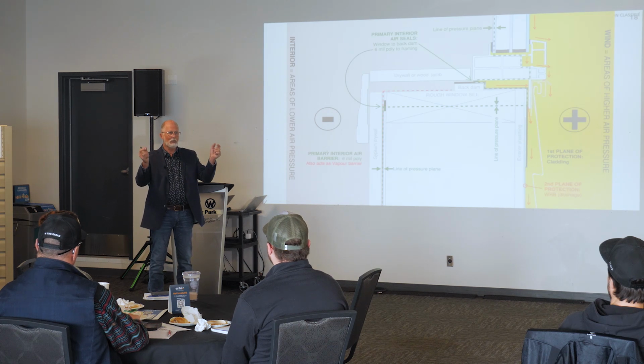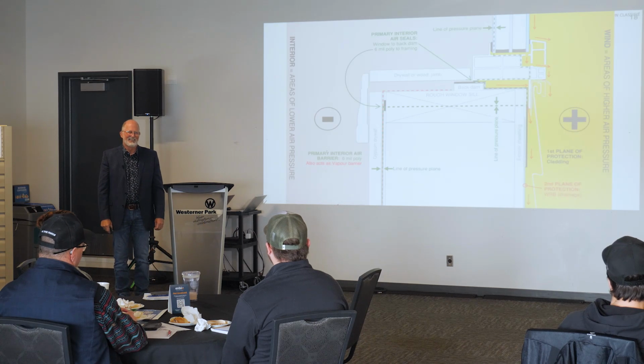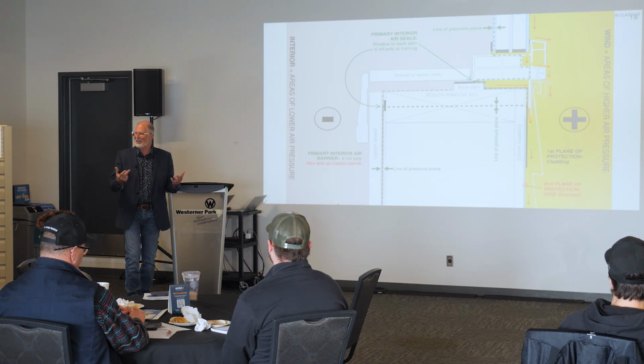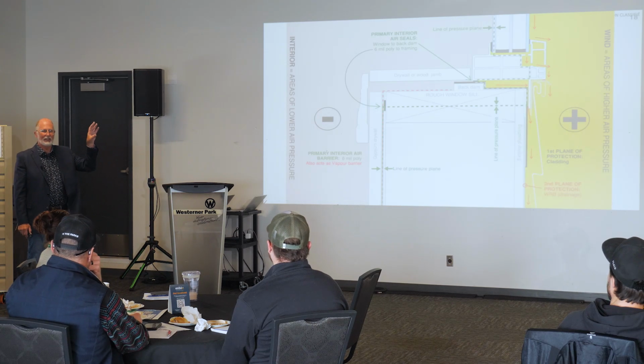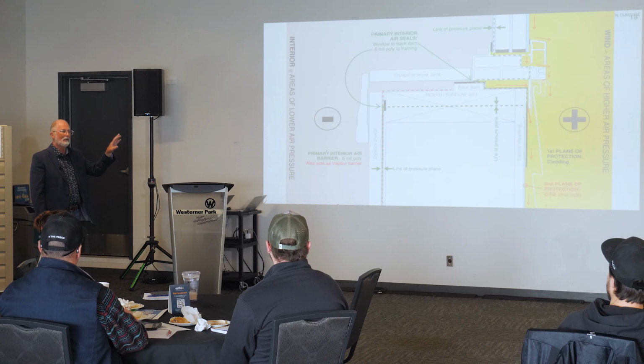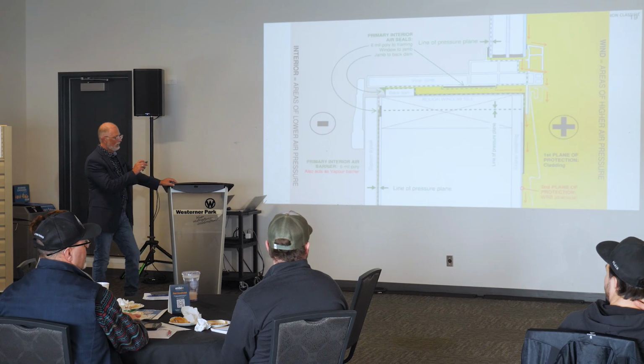The seals break, water gets in there. Whose fault is that? You ever had a framer come back and say, oh, that's my fault, I'll warranty that, right? So things happen like that. So that's why treating a window as porous protects us so that long term we don't have that risk associated with what can happen. Question, sir.